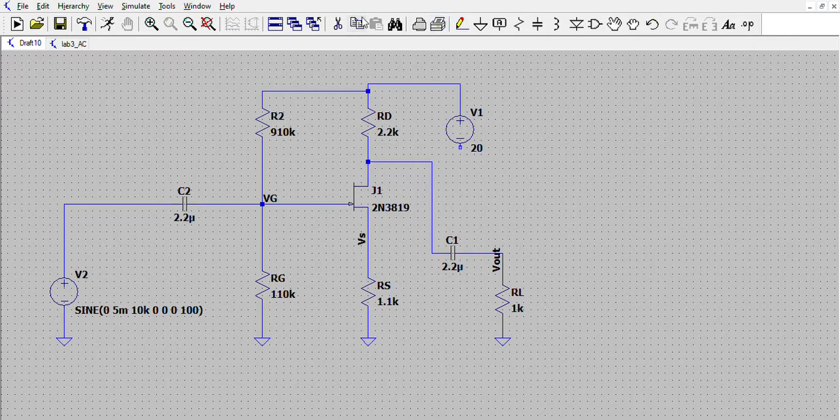Okay, and put label net VD. So the last one is V in. It's supposed to be a small letter, but it's okay. And then this is the VDD. Label net VDD. So the VDD is supposed to be there.